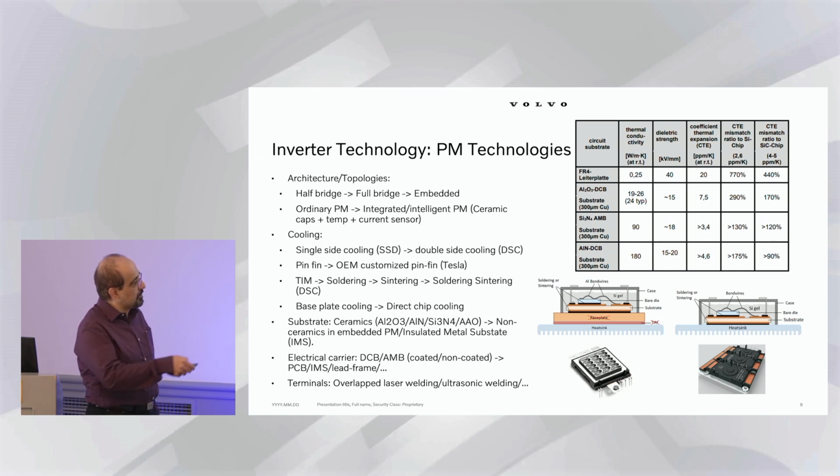And for terminals, we know that it's very important to have an overlap terminal to minimize the parasitics. Right now we are using laser welding, but in the future we are going to do ultrasonic welding, and we have seen better results. We have tested that one.